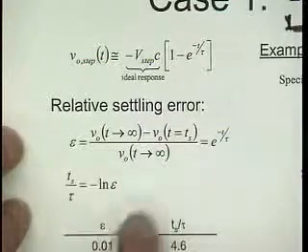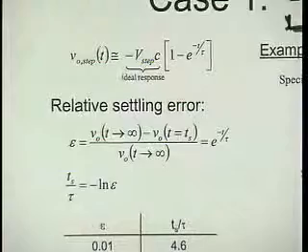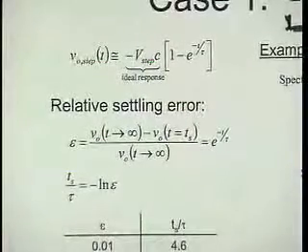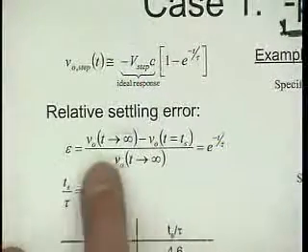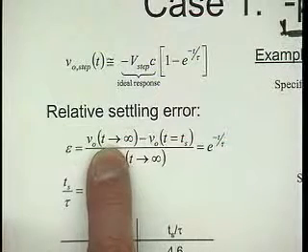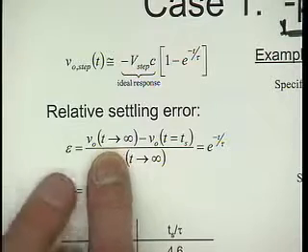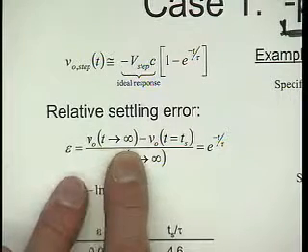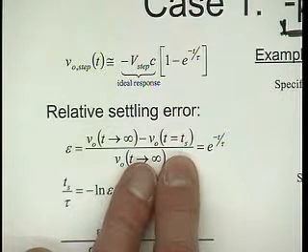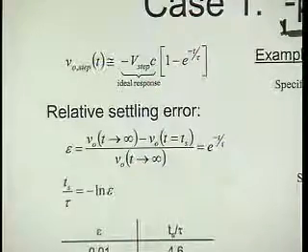And so now what we usually care about is the relative settling error. We don't care about the settling error in microvolts or something like that. Most of the time we want to have the relative error not to be bigger than something, right? So we can calculate that. So the relative error is simply the ideal output, which because we neglected the load resistance, is simply the output that we would be getting after waiting for infinitely long, minus the actual output. Well, that's the output taken after not waiting infinitely long, but waiting for TS, where TS is the settling time, right? The allocated settling time.